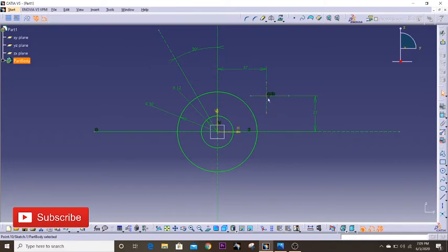Since you can see it as a square, as a plus point, I'm going to have to make it a construction point, because we're not exactly using it to build. It's not an actual sketch, it's only going to help us in constructing the circle. So I'm going to select the construction / standard element to make it a construction point. There you have it. It's now a point, not a plus point, if that makes sense.